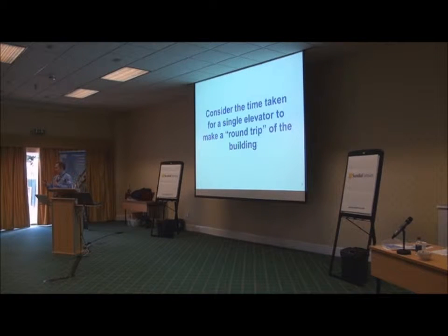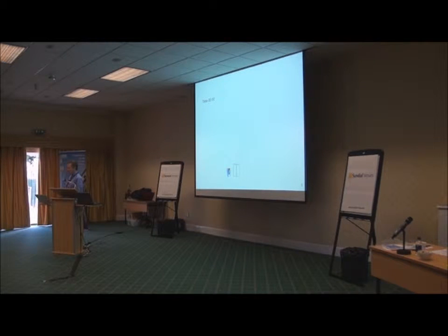So let's just revise what a round trip time calculation is without looking at equations, because we don't like equations. This is a lift at the ground floor at time 0, and a whole load of people get into the lift. And you go up, and someone gets out, and more people get out. It's very exciting, isn't it? It's better than paint drying, but okay. And then we've finished unloading people, and the car comes back down to the ground. That was about 2 minutes in my example. And so in this instance, the round trip time was 120 seconds.